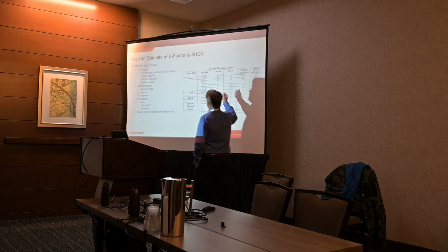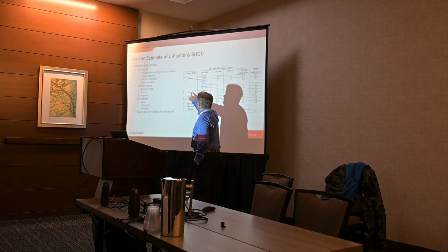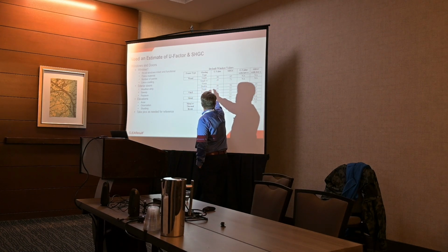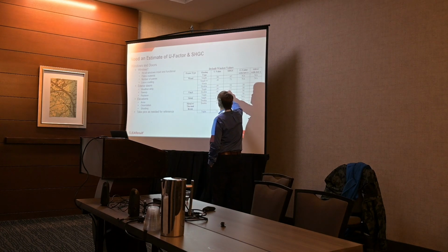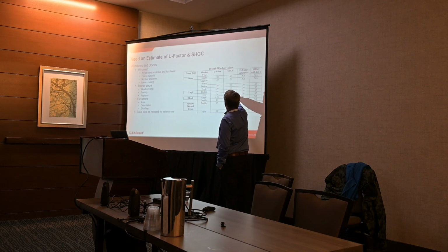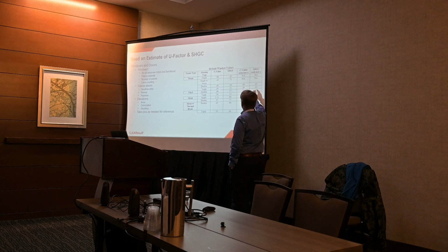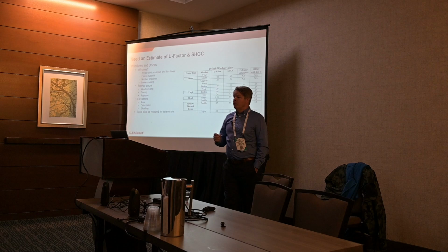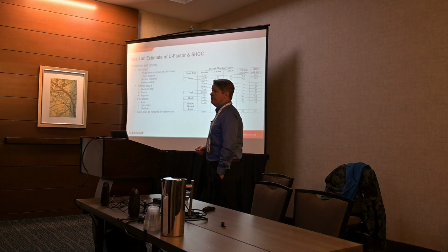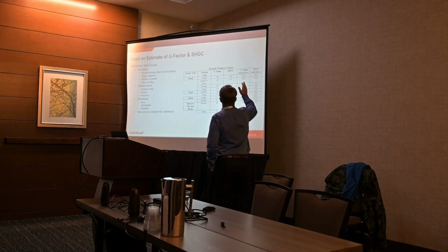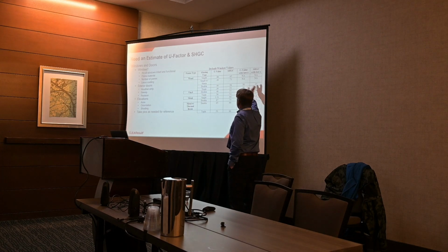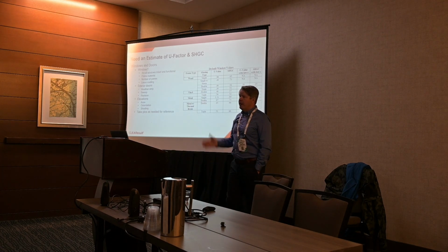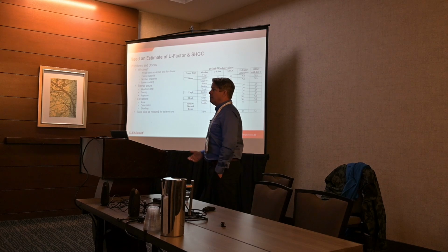So let's say we have a vinyl double pane window, right? We can come down, there's vinyl, there's double pane. The U factor is 0.46, and the solar heat gain coefficient is 0.57. But if it has a low E coating, it drops significantly to 0.36 and 0.45, right? Windows are the main driver of cooling loads, so that's important, right? If the solar heat gain coefficient is much lower or much higher than we think it is, then our calculation for cooling is going to be off significantly.